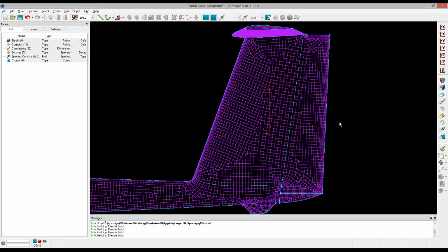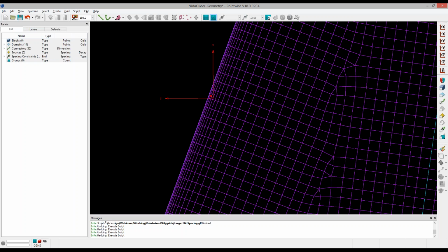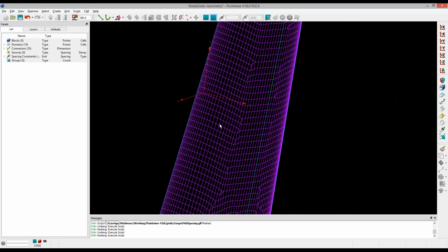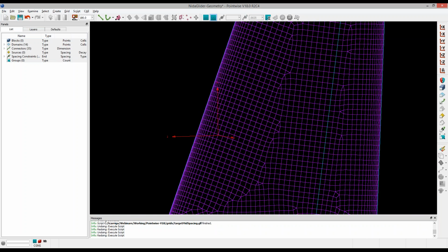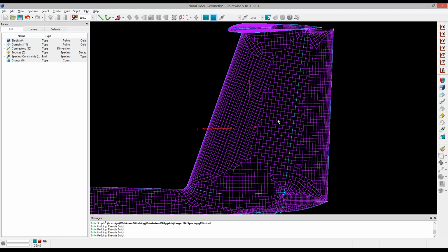This surface mesh, and I'll give you a tip. If you're using the quad dominant technique, you're going to get your best results by keeping that domain as uniform or isotropic as possible. Does that mean you can't do any sort of refinement? No, absolutely not, because I'm doing refinement at the leading edges of these surfaces and at the ends of those connectors as well. The only reason it looks as uniform as it does is because I changed the distribution and the number of points on those connectors. It's a much smoother transition from the clustering at the ends using that growth rate of 1.2 and targeting that 25 millimeter resolution on the interior, and it updates everything for me automatically. I'm very happy with this result, and I think you will be too if you use a technique like this with the quad dominant surface meshing algorithm.